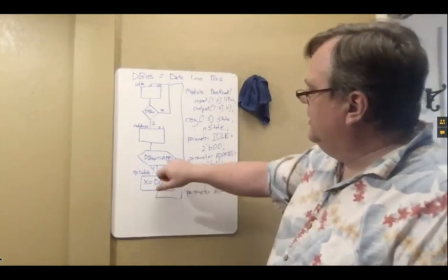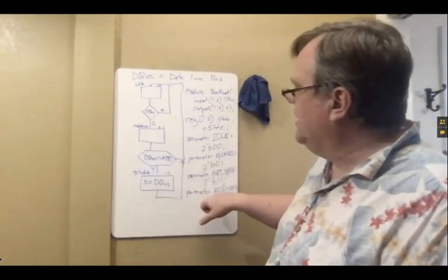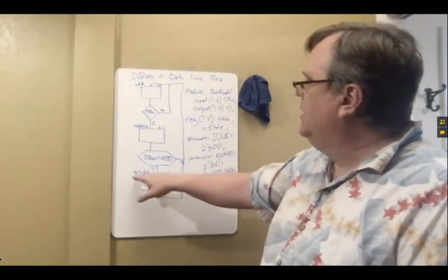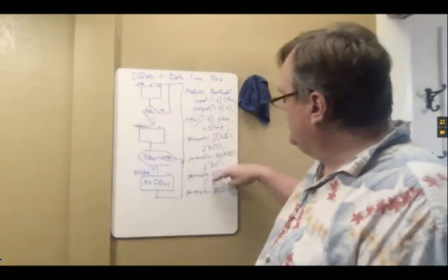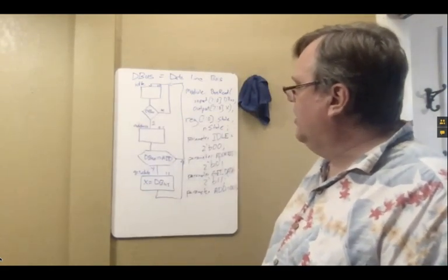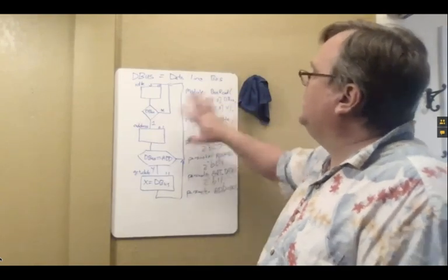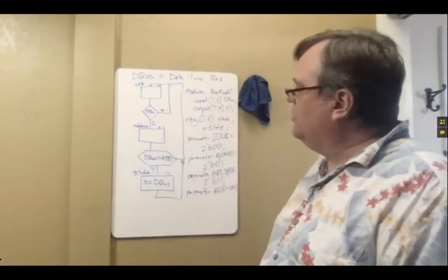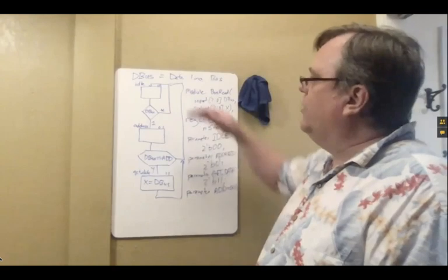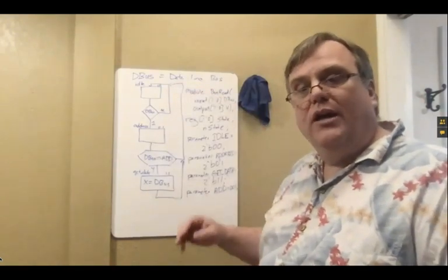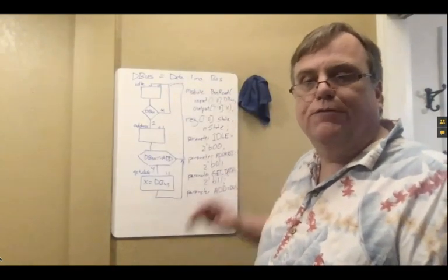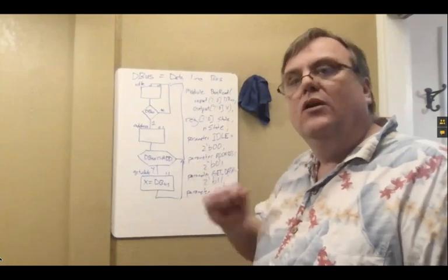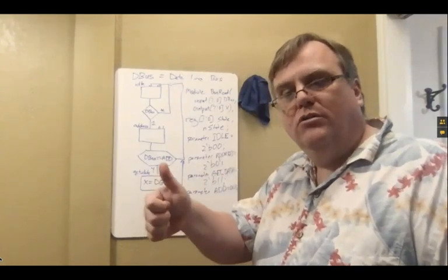So now I've got ones add. I've taken care of it with a default value. I've got each of my state values set in here, and I've handled my inputs and my outputs. So now all I have to do is create the necessary register file and then do the next state logic from it. So far, so good.